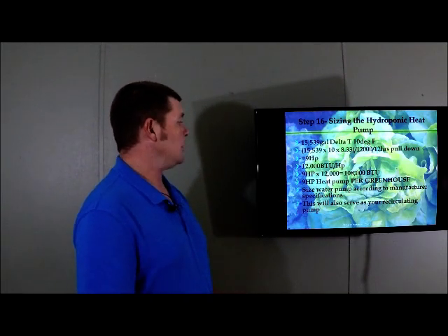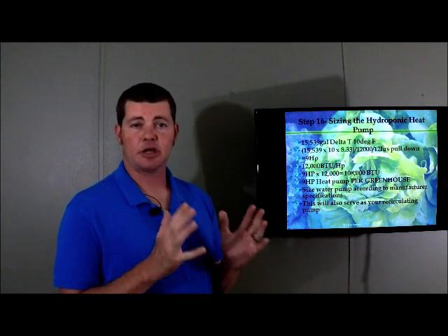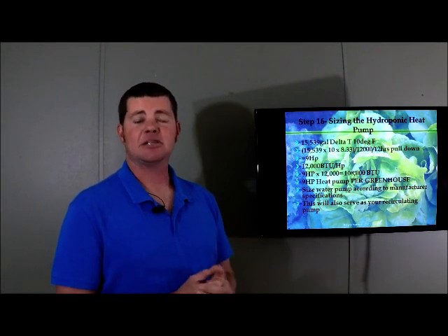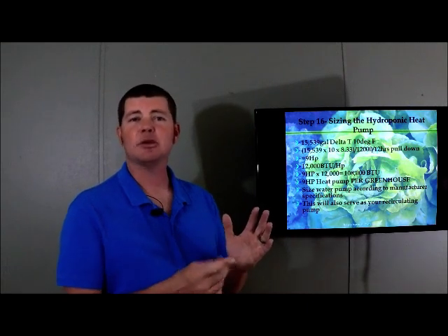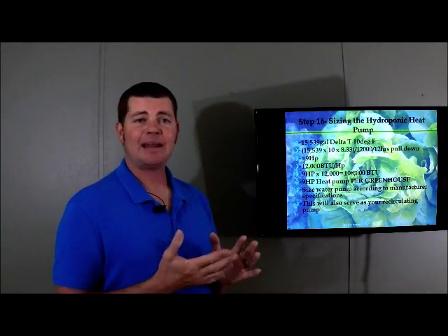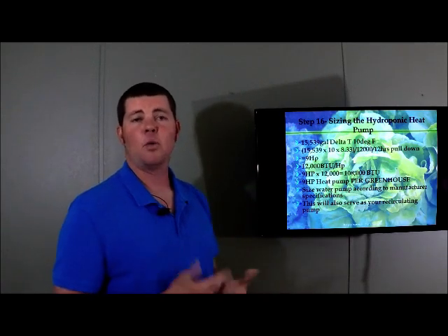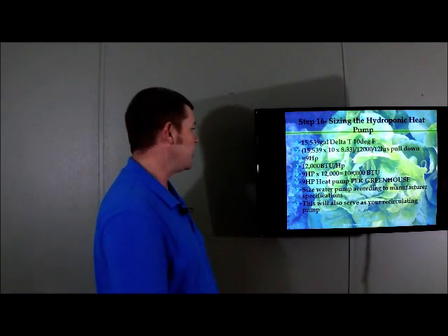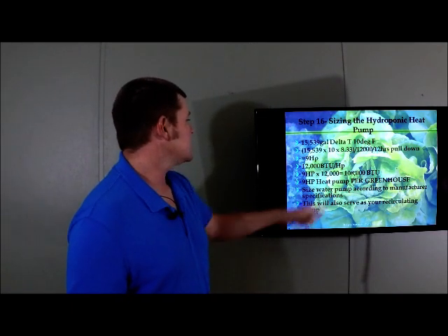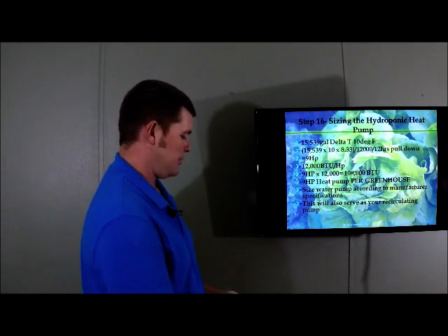Size the water pump according to the manufacturer's specifications, because they have a minimum and maximum flow rate to go through that heat pump. As long as you're within that parameter, it will work correctly. You won't freeze up the unit or burn up the unit. And again, that's going to be much higher than the once per 12-hour calculation we did on the last slide as a minimum requirement. Size the water pump, we just said that, and this will also serve as your recirculation pump.